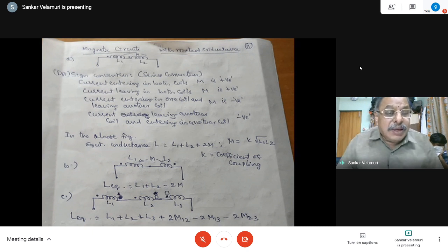Because as I said yesterday, inductance acts as a non-linear element sometimes, a linear element sometimes, and other things. The element which obeys Ohm's law is a linear element, as I have stated. But in DC circuits, under steady state analysis or under initial conditions, neither inductance nor capacitance are linear elements, surprisingly. But in the AC steady state analysis, you are going to identify them as linear elements. So for that, first, the principle of magnetic circuits is necessary.